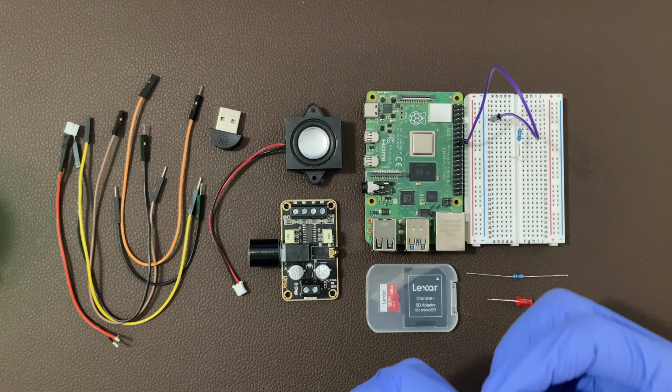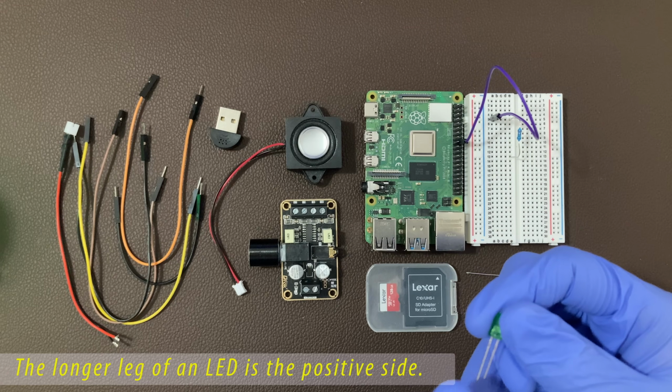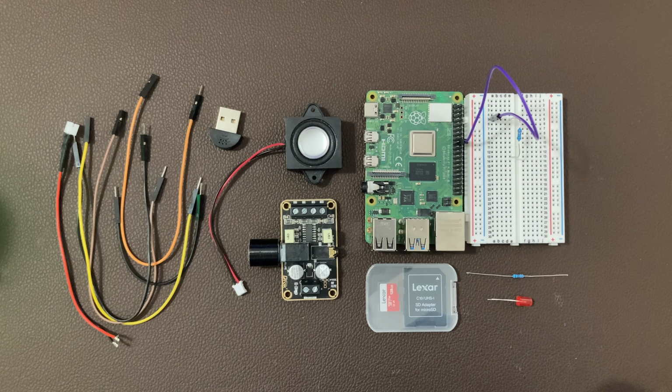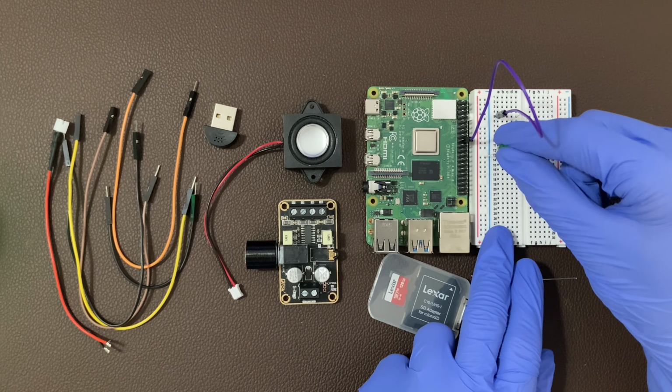Now let's do the LED. A quick note about LED is that we have to connect from the positive to the negative side. So the positive side here is going to be connected to the resistor. And then the negative side here is going to be on the ground.